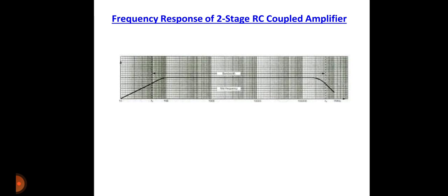Similarly, if we see a transformer coupled amplifier, there will be a peak over a band of frequency. It is due to the transformer present in the transformer coupled amplifier. Therefore the frequency response is not as good. In direct coupled amplifier there will be no gain fall in low frequency. Therefore it is used for the amplification of low frequencies. It is mostly suitable for low current amplification.